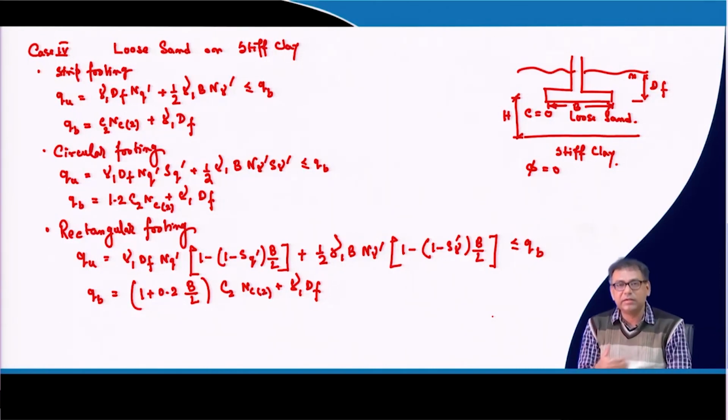But actually when this theory was developed, no recommendation was given on what to do if there is a local shear failure in the soil. Now, one thing I have mentioned is the compressibility effect part. If those data are available, then you can check whether you need any compressibility corrections for your soil case. If you need that, then you put those corrections here.